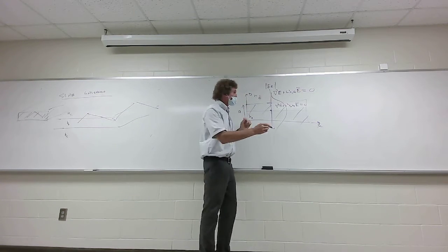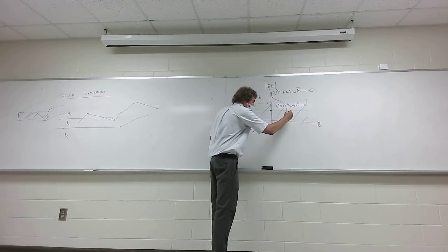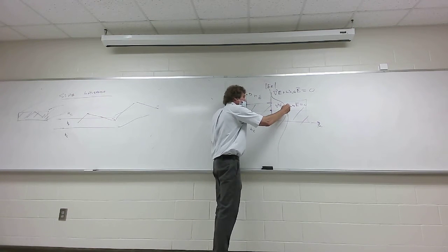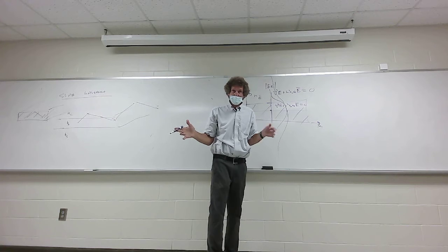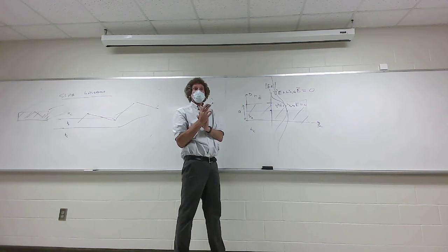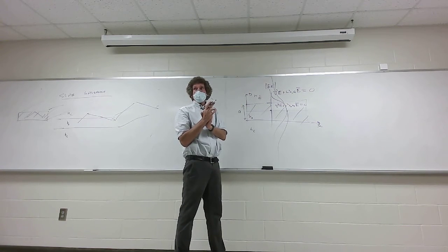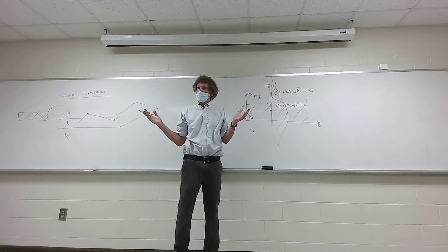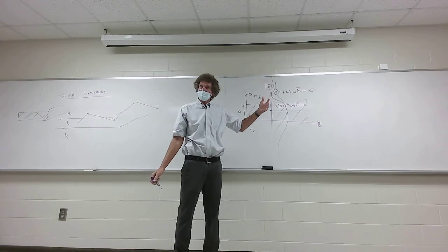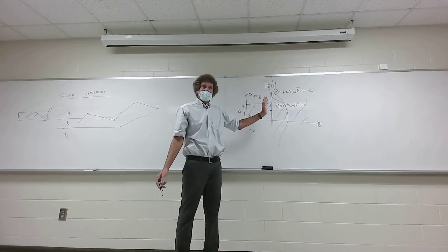All right? I'm just trying to give you an appreciation. Now, the lower the frequency, the more gradual this thing comes down. All right? I know you're thinking that seems insane. That's what really happens, all right? And there is no cutoff frequency for the 0 mode. That's the lowest order mode that can propagate. In Dr. Wimmer's book, he calls it TE0 or TM0. And to you, you're like, huh, what does that mean? It means this. No matter how low the frequency, things will propagate.